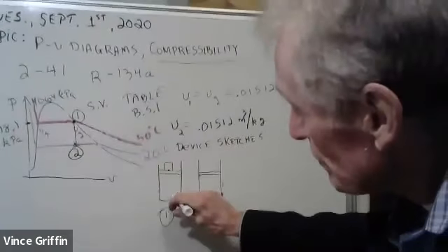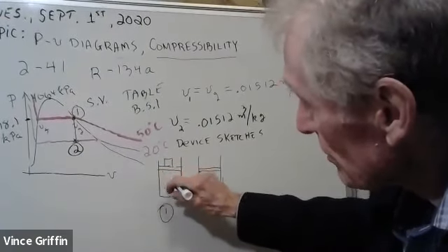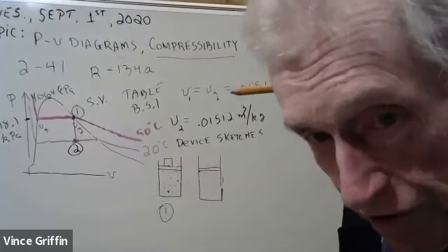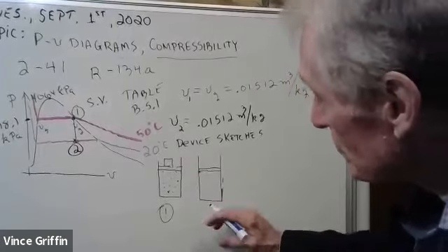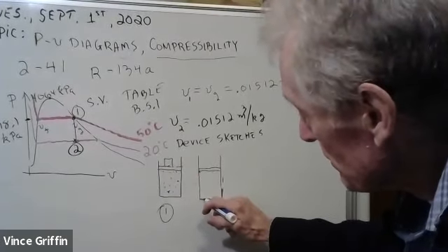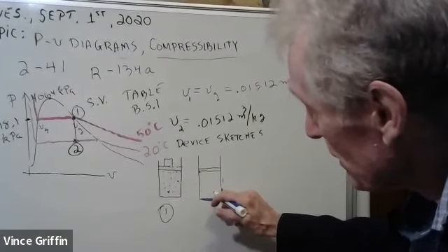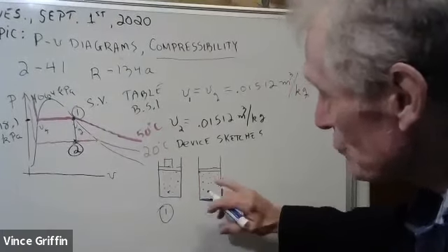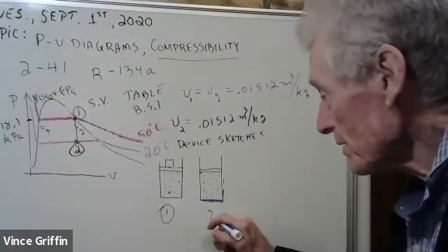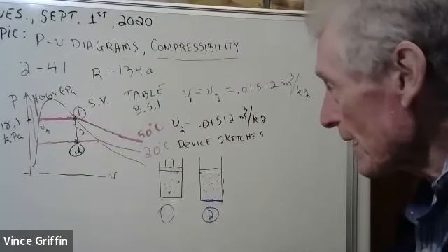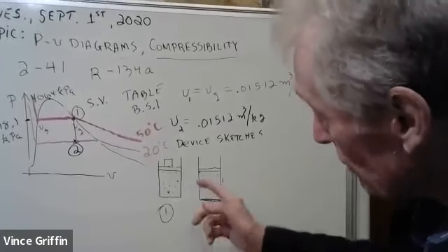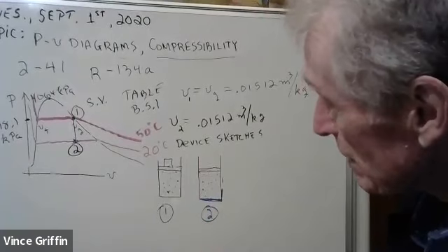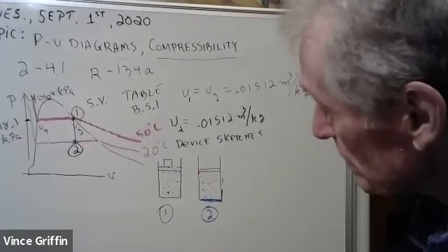This one here has got nothing but vapor. Here, put some molecules of R134A in there. See, those little dots show up? Yeah, there you go. But state 2, look here, you got some liquid R134A here. And you got little dots here. You got R134A vapor, but you have a mixture at state 2 of vapor and liquid. The volume's the same, but the pressure is different. What about the temperature? Ooh, it got colder.